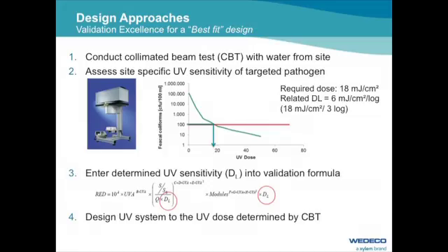This is actually the procedure on how you can determine the site-specific conditions. So you take a water sample from the site, determine the specific dose-response behavior, enter it into the validation formula, and then you can design the system accordingly.